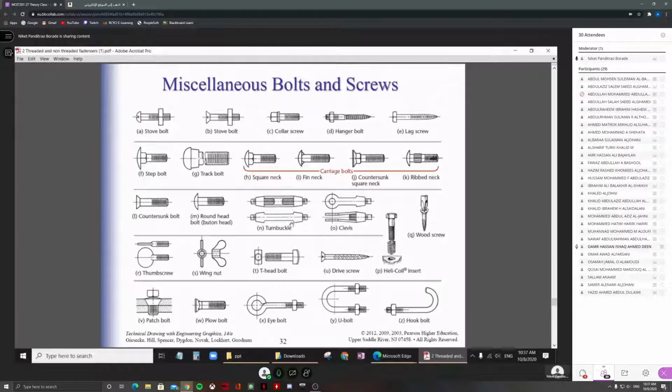You can see in front of the ACX building also, there is a kind of tent or shade, and at the end you have the turnbuckle. You keep it a little loose so that you can attach it, and once it is attached and fixed, you can use the turnbuckle to make it tighter because it should be stable in the wind. That is the reason.